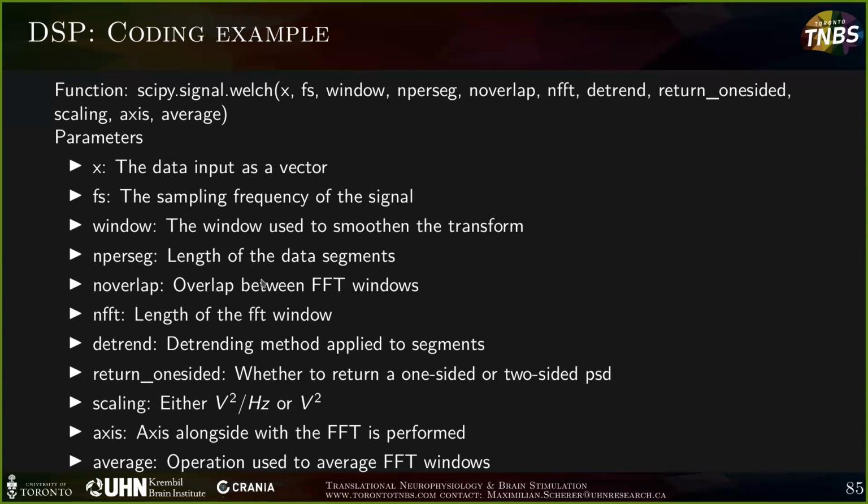And then, of course, since this particular example, I chose a Welch method. It does concatenating data chunks out of the data you provided it for the averaging later on. It even overlaps them to basically adequately represent whatever is happening at the junction between two of your data chunks. And that's basically all the parameters you would have to set. All of those other parameters are quite situational and rarely ever have to be adjusted.